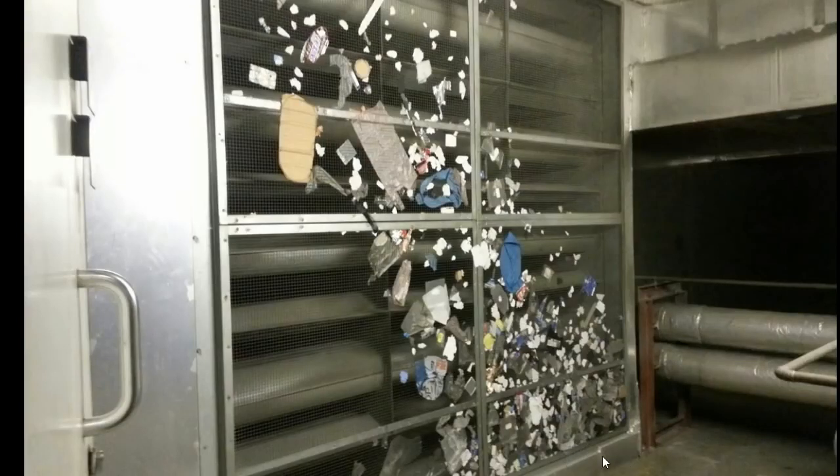This intake was positioned near the bins of the building, and if this mesh hadn't been there, this could have potentially been sucked into the fans. It should have been picked up by the filters on the other side, which we'll look at in a bit, but it still could have built up on the inside and caused some damage in there. So it's good to have a grill on the outside first to catch anything and stop any animals or anything that could cause damage getting in there. And it's obviously important to clean this off periodically as well.